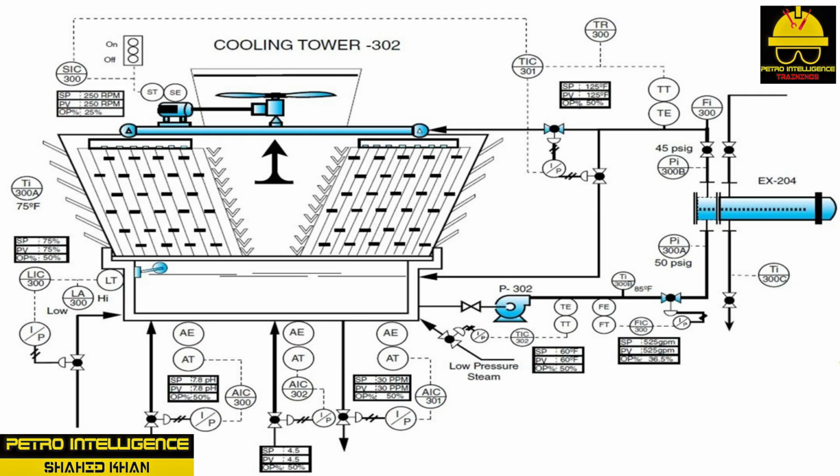pH control is an automatic control system that continually analyzes the pH in the basin and adds small amounts of acid or caustic to maintain operational requirements. Water treatment: the composition of the chemicals used in the water treatment system is designed to control scale, algae, corrosion, wood decay, and to help suspended solids to precipitate out in the basin. Basin level control: the water level in the basin is controlled as a level element, and a transmitter sends a signal to a controller.